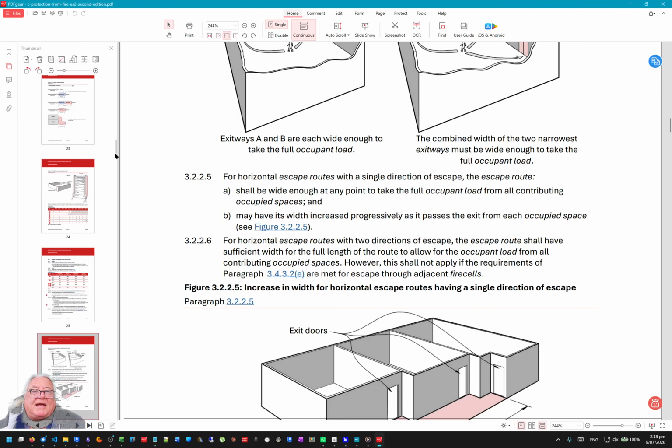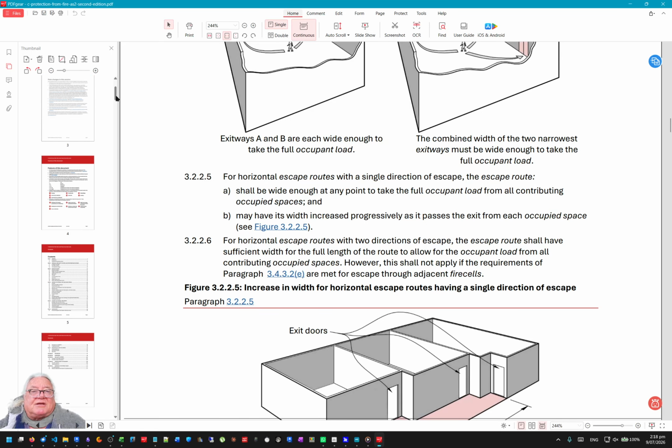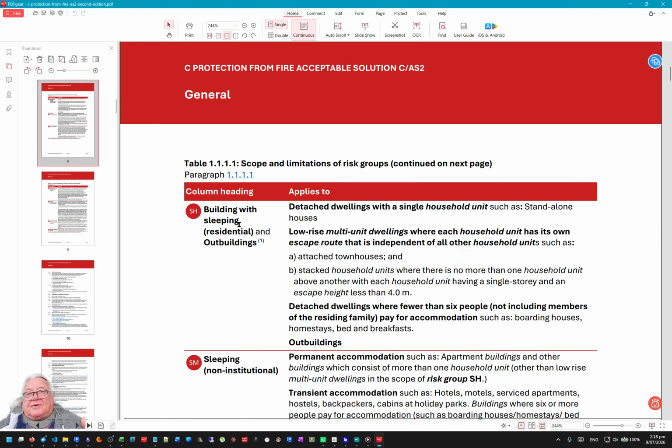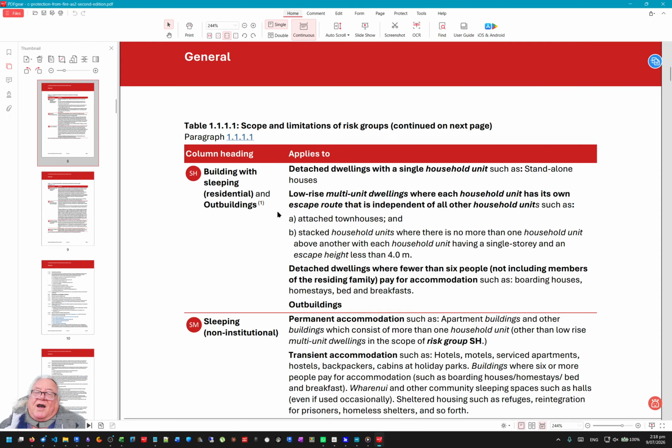So if we go into page number 8, that'll tell us about the category 3. So with the FAR code, you have different risks. So if you've got people in an office and there's a fire, everybody's awake and everybody can suddenly say, well, there's the nearest exit, I'll go and run over there and get to it. But if you've got people who are sleeping, they're actually unconscious. So if suddenly they wake up and there's a fire, they're going to take a lot longer to react.